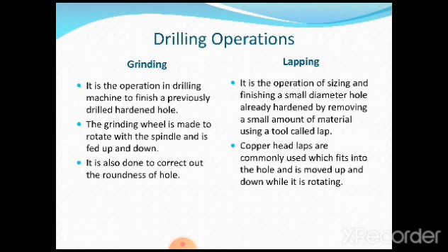Now the next operation coming up is grinding. We need to understand that though we carry out the special operation called grinding in a regular grinding machine, it is sometimes necessary to carry out grinding in a drilling machine also. It is the operation in a drilling machine to finish a previously drilled hardened hole. To some extent it is possible to go for grinding, which, you know very well, is again a finishing operation.